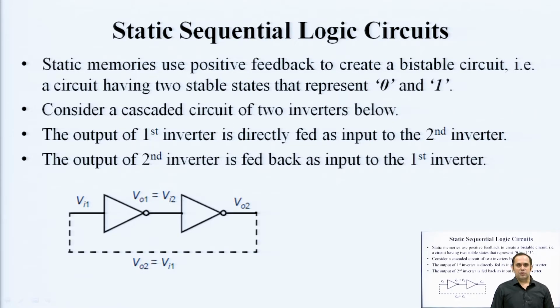If you store the data, by data I mean the current state of the output is preserved or latched onto a certain circuit, so that it can be used at a later stage for obtaining the next state of the system, that is the storage element of any sequential circuit, which is the heart of a sequential circuit. That is why most of the analysis and discussion of a sequential circuit is related to how data is latched. When we differentiate between different sequential circuits, we are actually differentiating between different types of memory circuits.